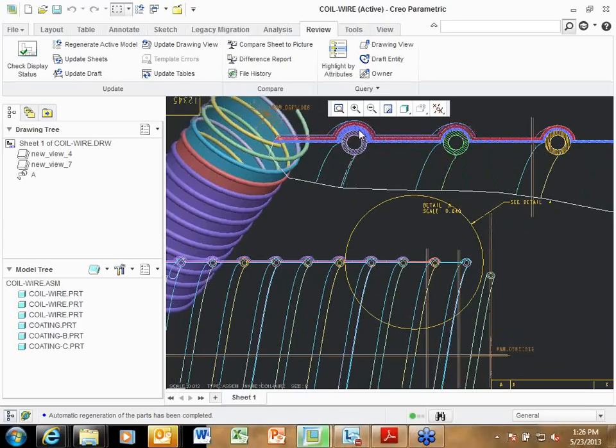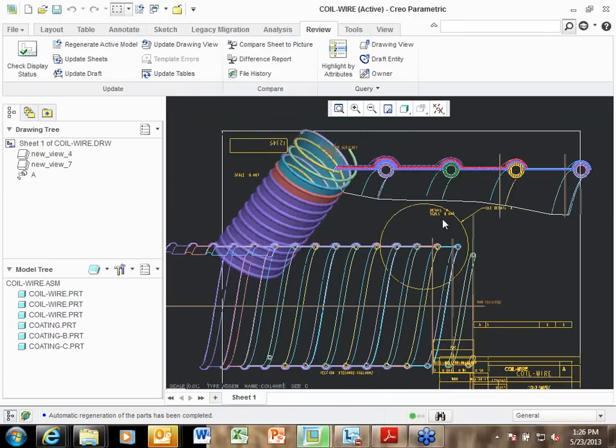And that's what I did by actually color coding this with all these different colors. So you can see the double overlaps where here you have a single overlap. And so you can see that as it wraps through that cross-section going forth, because that's the way they truly did it in manufacturing. So it wasn't until we actually cut this particular hose laterally and actually seen that, it wasn't there until I picked up and said, oh no, our model's completely wrong, because we're not getting the overlaps that we're seeing from each one of the coatings that were actually going around. So we changed that, and that's what we ended up with, and it works fine.